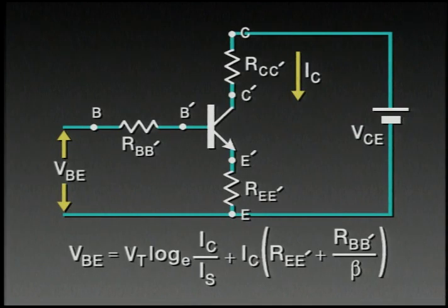In the center, we have the ideal transistor with terminals E dashed, B dashed, and C dashed. Connecting to those terminals are what might be called the approach resistances, most importantly the base resistance RBB dashed, the collector resistance RCC dashed, and in the emitter usually a rather small resistance REE dashed, which is often negligible, being sometimes much less than an ohm, very rarely more than 10 ohms.